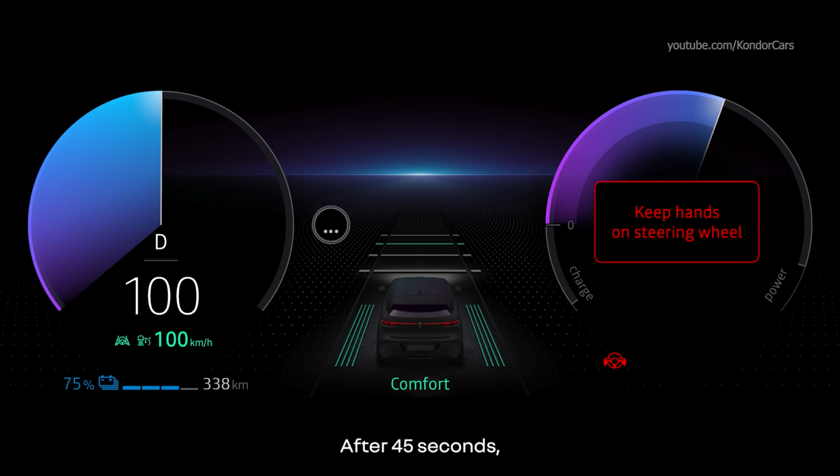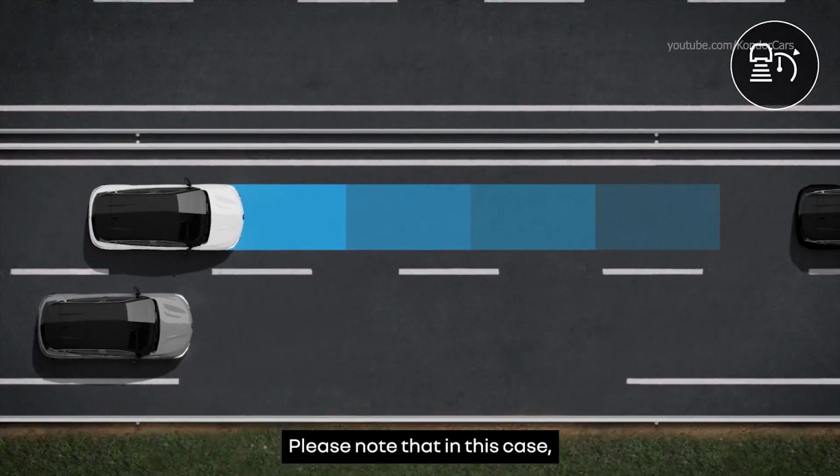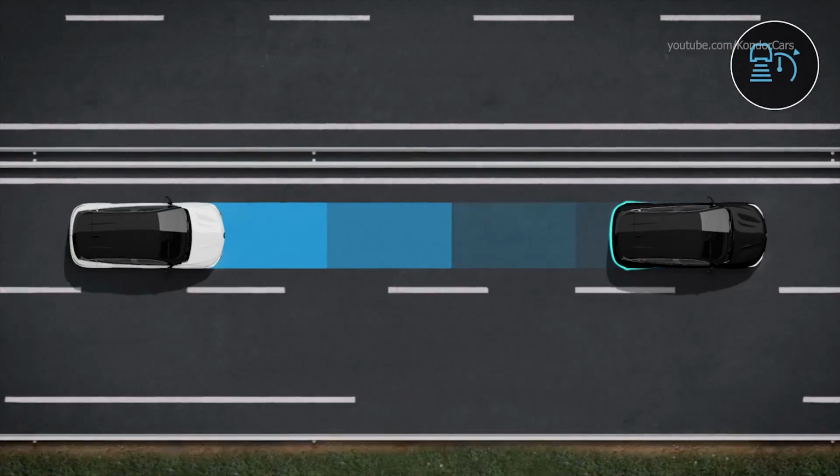After 45 seconds, all audio sources are put on standby and the audible warning is continuous. The indicator light goes out and the message "Lane keeping off" appears in red on the instrument panel. Lane keeping is then switched off. Please note that in this case, the stop-and-go adaptive cruise control continues to operate.